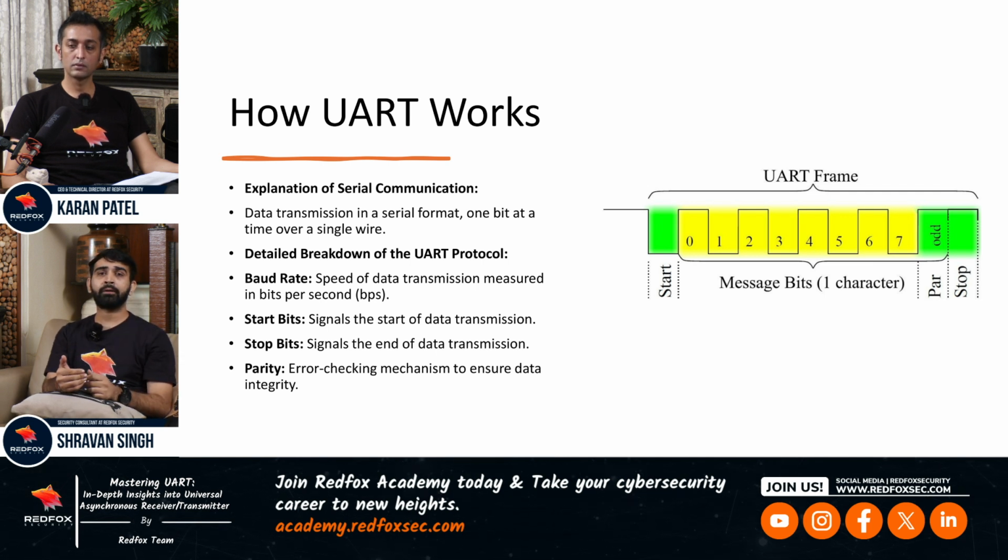If you have access to UART functionality, then there is a dedicated UART baud rate from the company itself. If you have access, say 57600 for example, then data will be displayed as per the boot, kernel, images, and the root shell access, everything will be displayed. But what if the company blocks it? Sometimes they disable the UART pins, and because of that the baud rate also does not work. So it depends on how the companies react to the security concern.